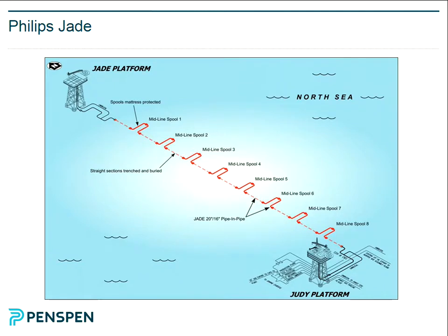Some years earlier, an operator tried a technique of allowing lateral buckling or snaking. I don't know if you've covered that in any of your lectures. Effectively, they laid the pipeline in a snake formation, and then operated it and allowed it to actually move across the seabed, but it failed catastrophically because the snaking configuration that they planned didn't actually concentrate the buckles.